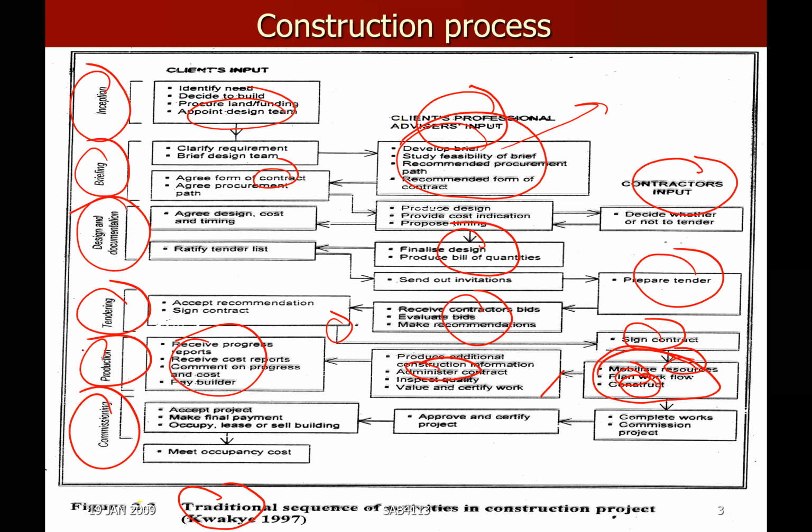Then lastly, commissioning. Commissioning or testing, handover, everything is put together because this is the final acceptance of the project or handover. For the contractor, for instance, they need to come up with all kinds of documentation, manuals for maintenance, as-built drawings, and all kinds of things. Rectify the defects so that the project can be certified by the consultant,